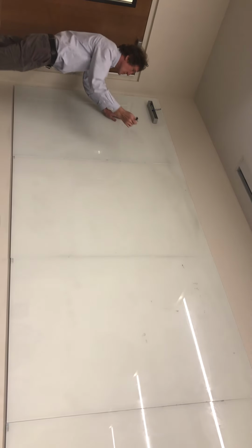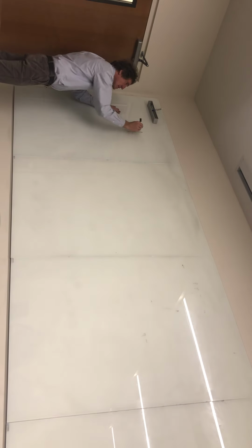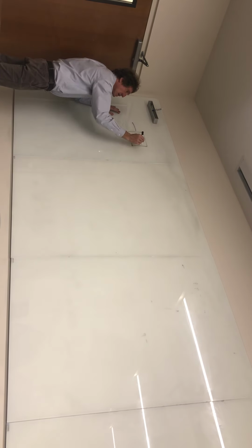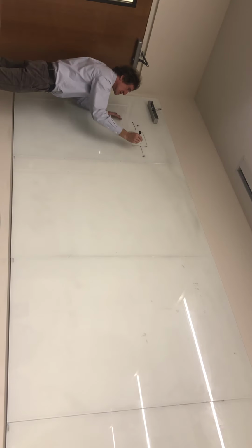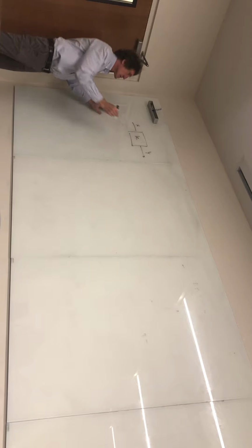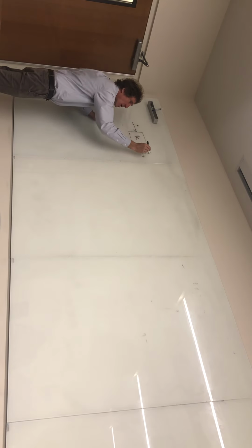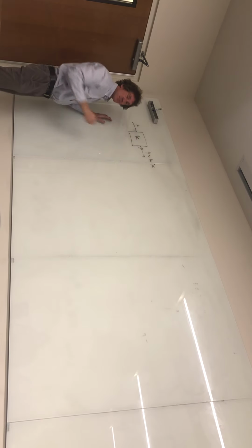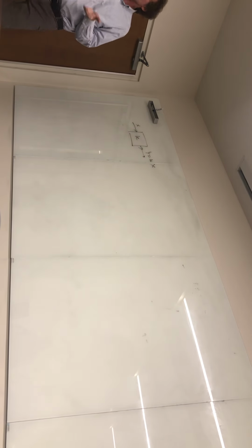Wow. What I'm gonna do is put over here some terms that I'm gonna keep going to. And I'm gonna just show you this. Oftentimes, we're gonna have a block that just has some constant k that you wanna multiply x in to get y. Are you with me? It's a block diagram. In x, out y, y equals kx. It can be in the time domain or in the s domain. Constant multiplication is a constant multiplication.